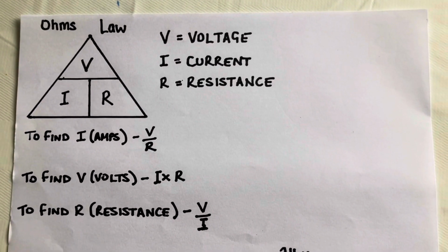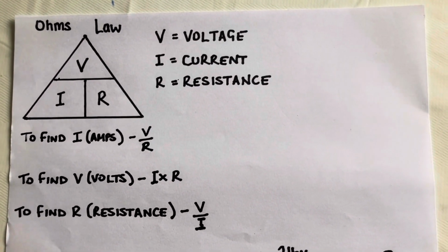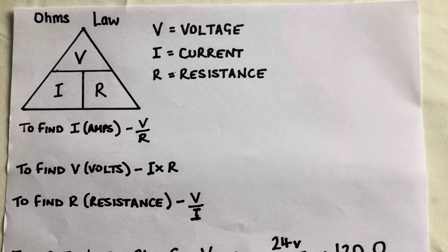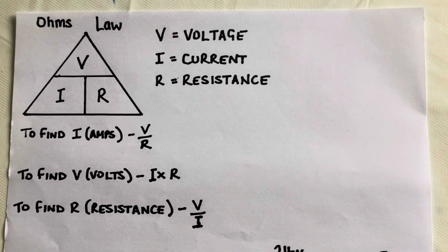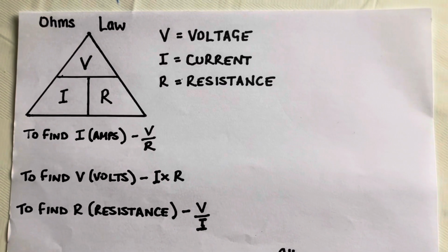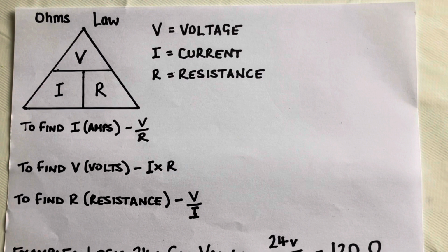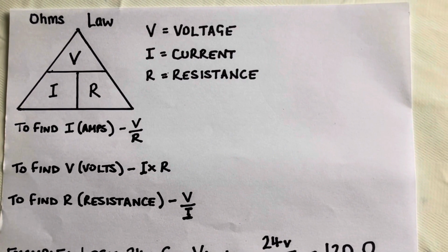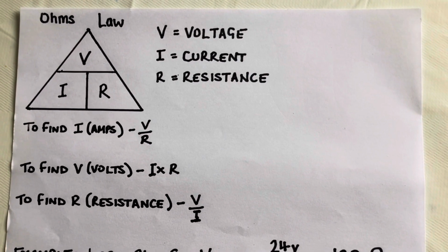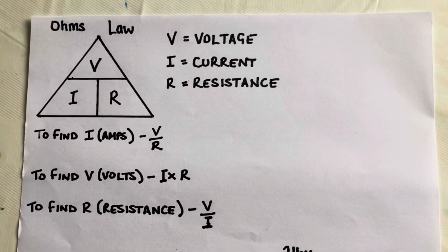It could be causing a safety issue, or it could cause a fault on the appliance. So we're going to go to the boiler now, and I'm going to show you how I test the boiler before I touch it, and then I'll show you some dead tests on components, which is handy to know before you even put any live power to it. Obviously, dead testing is a lot safer as well, so you're not actually working with live voltage, which is always a better way to work if you can. So we'll go to the boiler now and show you some tests.